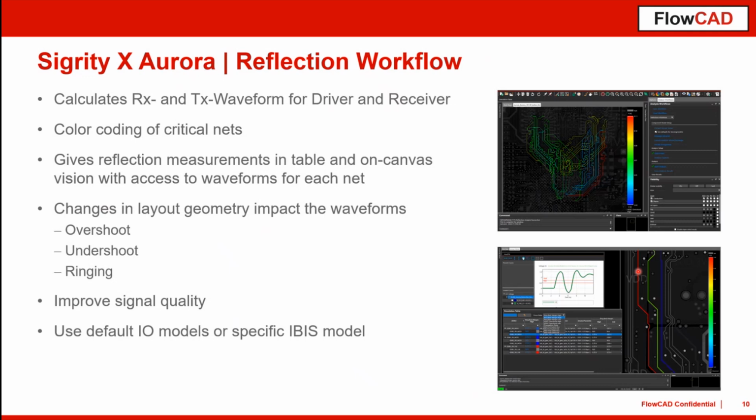And then you can analyze whether the ringing, the reflections, or whatever else still meet your requirements, or if you need to adjust some parameters or even to move some traces away. So if you have vendor-specific IBIS models on hand, you can attach them to the analysis, of course, as well.